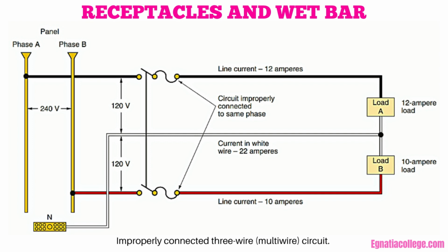All single-phase, 120/240-volt panels are clearly marked to help prevent an error in phase wiring. The electrician must check all panels for the proper wiring diagrams before beginning an installation. This figure shows how an improperly connected 3-wire circuit results in an overloaded neutral conductor.